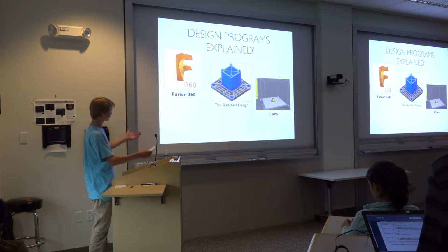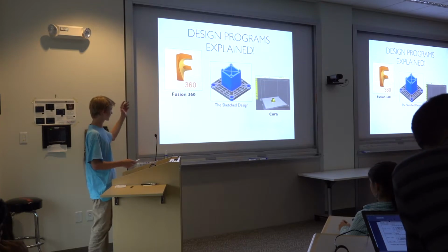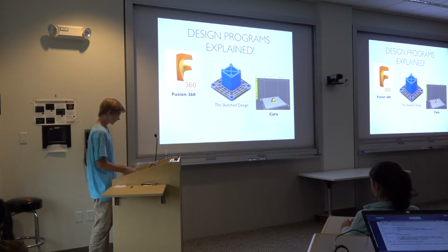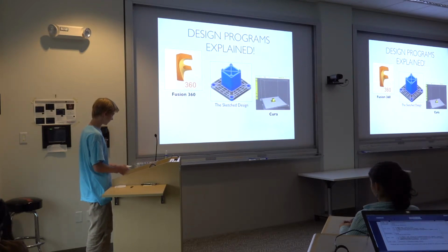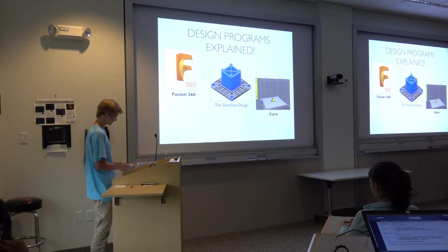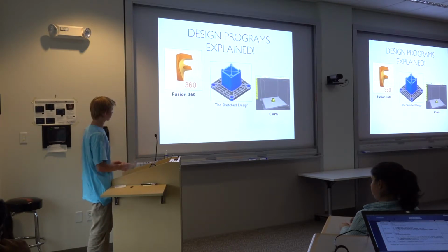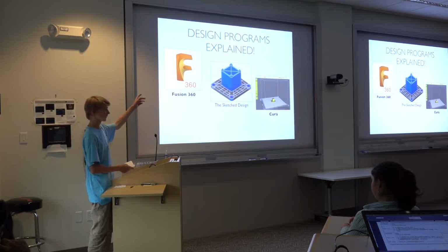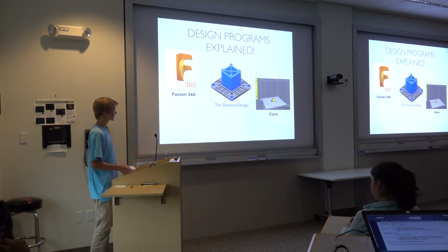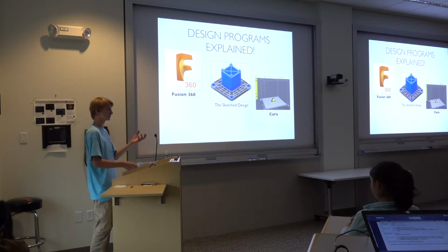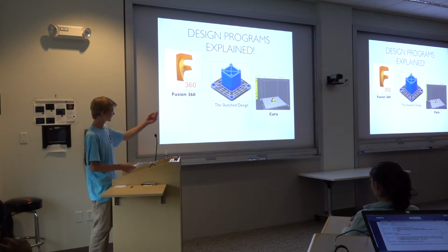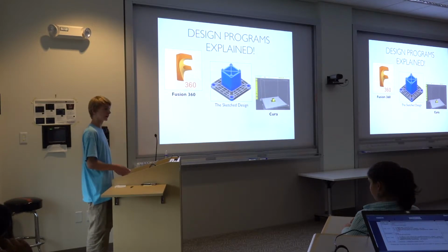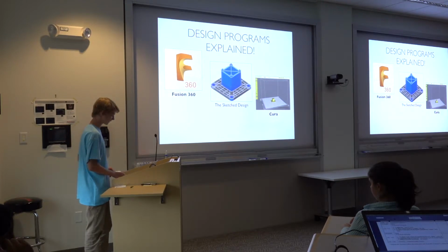These are the two design programs I used, Fusion 360 and Cura. Fusion 360 is a tool for product development that combines design and engineering. In the middle is a sketch design that I was able to use to build each part, and that particular part held a beam splitter cube by all four corners. I was able to export that into Cura, which is a program that communicates directly with the printer, so you can 3D print what you design.